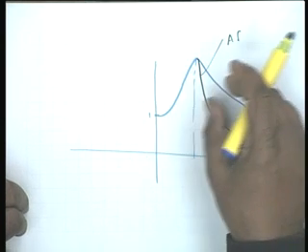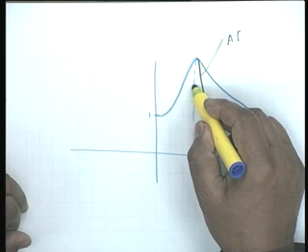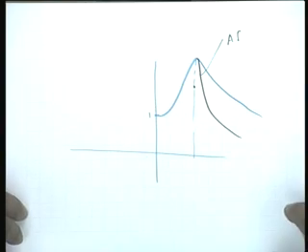It does not fall at the same rate at equal frequency deviations from the maximum. Let me make a prophetic statement at this stage, which you can also prove: near omega m, one thing is that the response here does not show arithmetic symmetry, it shows geometric symmetry. This can also be shown mathematically.